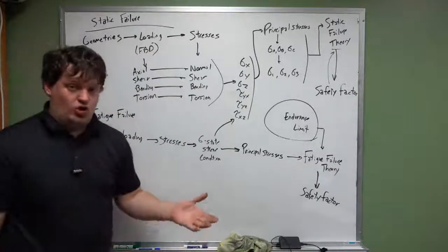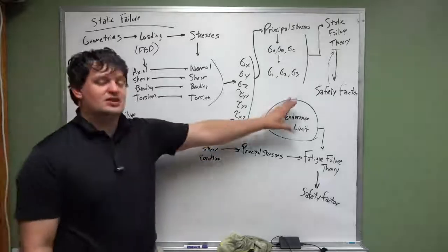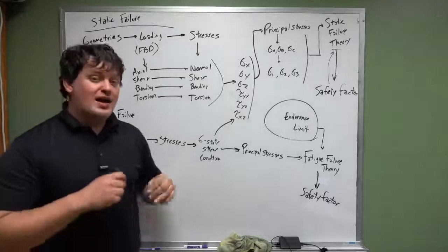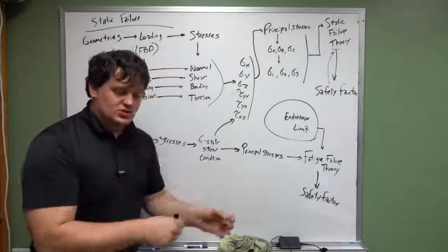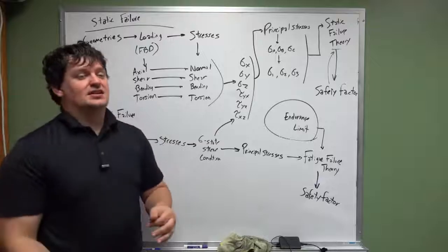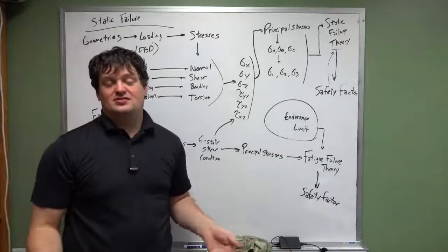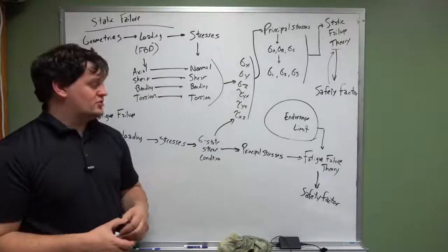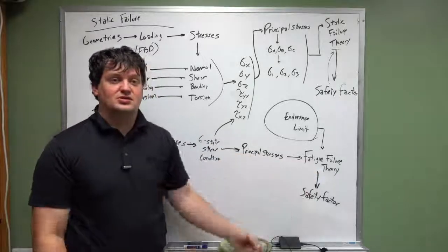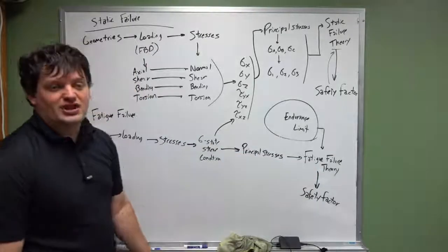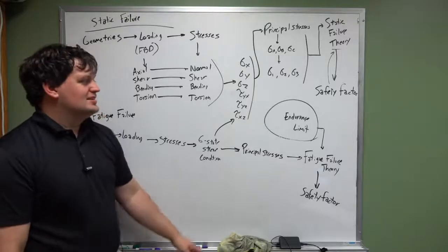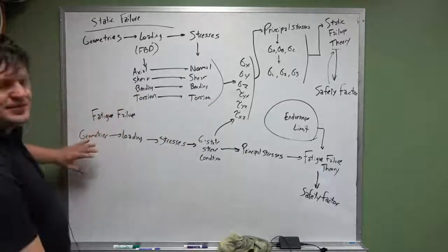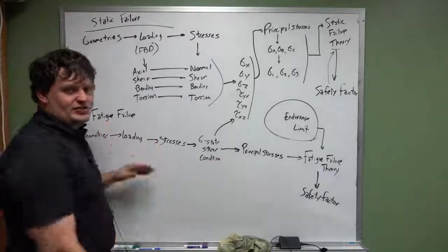So fatigue is not that hard if you understand what you're doing and if you understand what the endurance limit is. Okay? Remember, it's the estimate I gave you. If you ever were to test the endurance limit, the one you test is exact. It's not that first estimate where it doesn't depend on loading conditions at all. It is an exact one that you can use for any of your calculations. You can plug it straight into this as your endurance limit. No modification needed. So this could be a tested value. If you're going to calculate it by hand, you're going to use that second formula that I used, where it's got all those modifying factors.